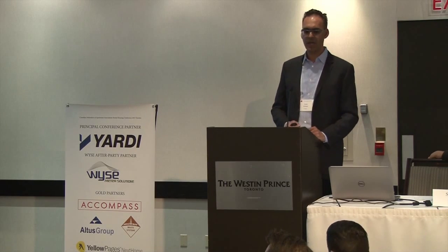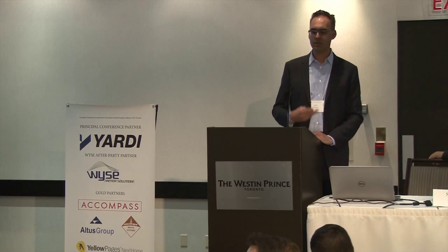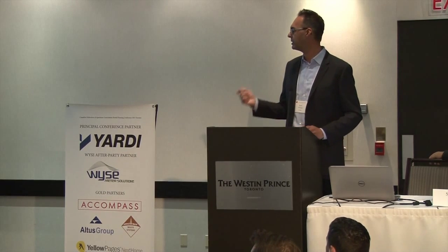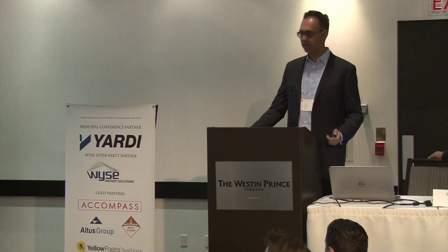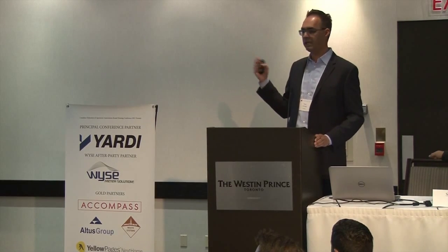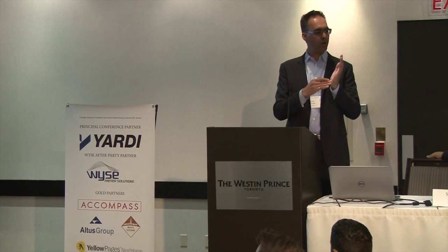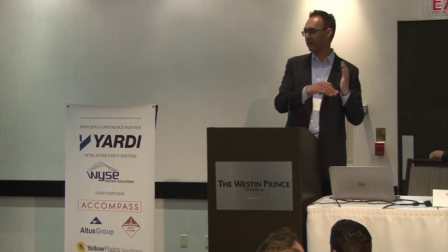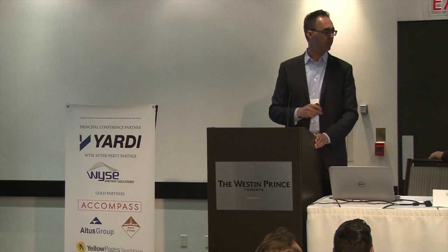When you have steel stud backup wall construction in your buildings, we always recommend doing some periodic testing to do some openings, check the conditions. Areas that are particularly problematic are around window corners. And as you can see in this first photo here, there are little foam gaskets that they use to make the joint between the horizontal sill and the vertical mullion of the window. And those fail after a while. So after 20 years of service, water that comes into the sill that's intended to drain out is getting caught in that corner, and it's going through the corners of the window frames, and it's going right into the wall assembly, like right in there.